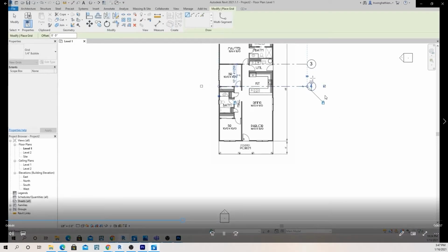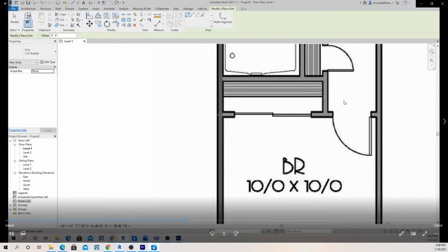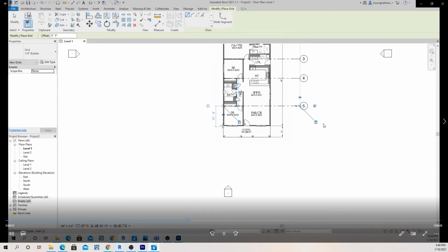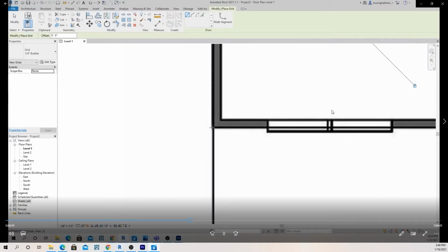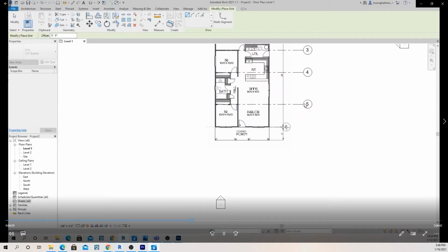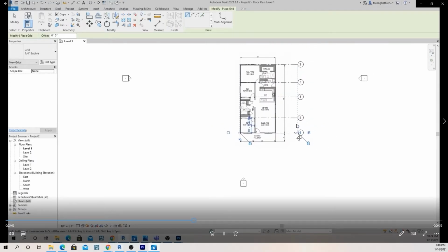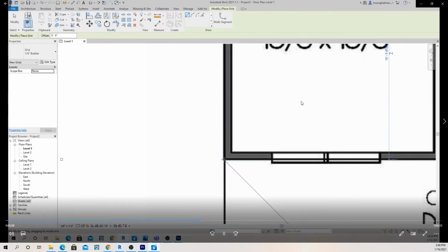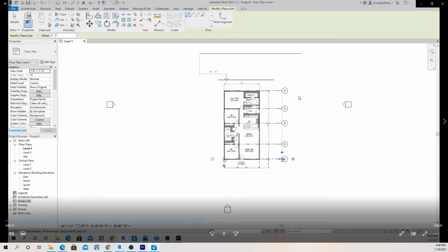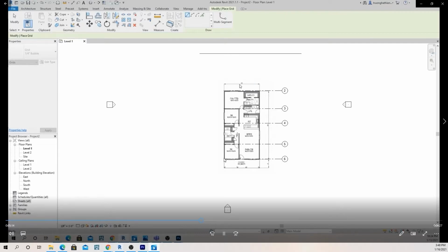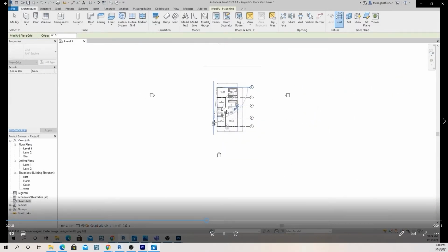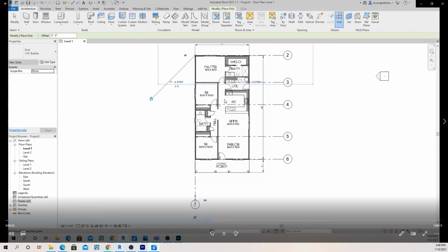And you should draw and keep it aligned with the other grid. After you click that one, you see the lock for the grid. When we move one grid, the whole grid moves together, and the vertical grid can be created that way. Usually for the outside walls you draw on the outside, and for the middle wall you draw in the middle of the wall.